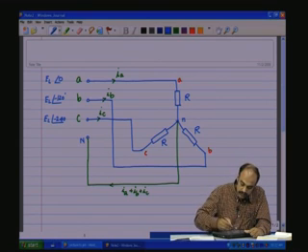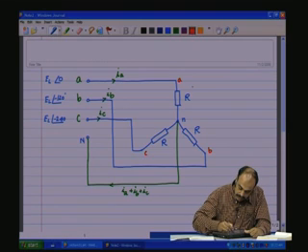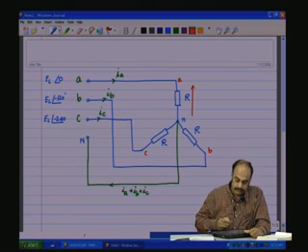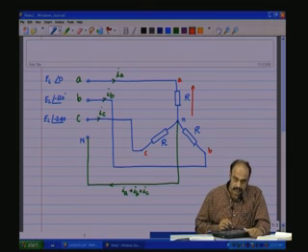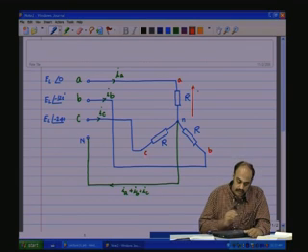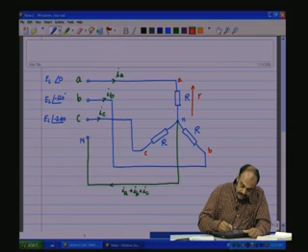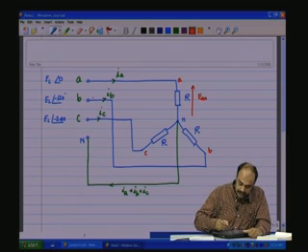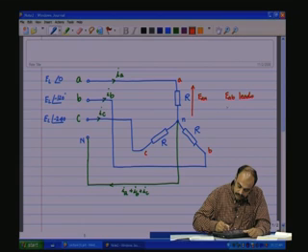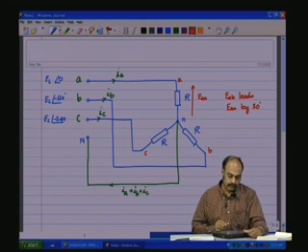We saw that the voltage across the phase, EAN, will be in phase with the line current in the case of the star circuit, which is IA, or IA into R will be EAN. However, EAB is going to lead EAN by 30 degrees. This we saw.